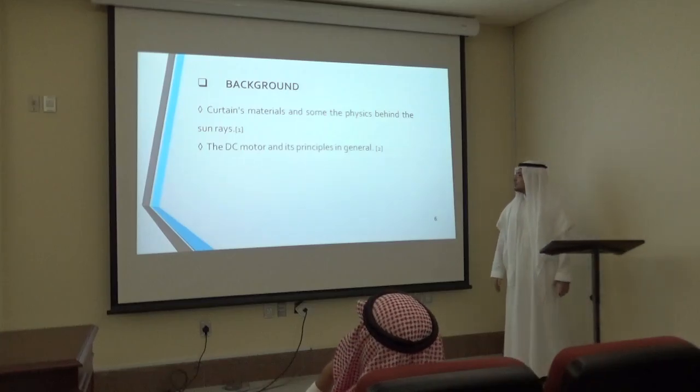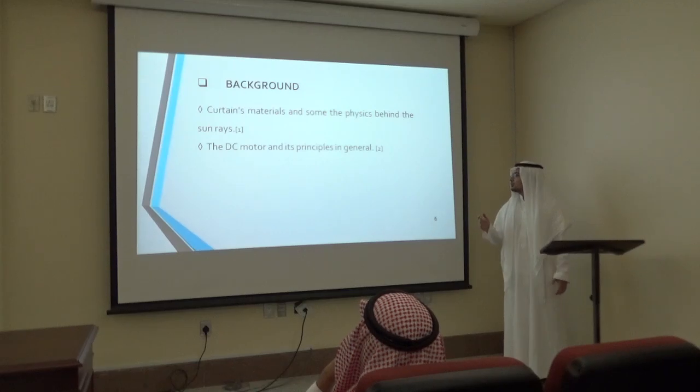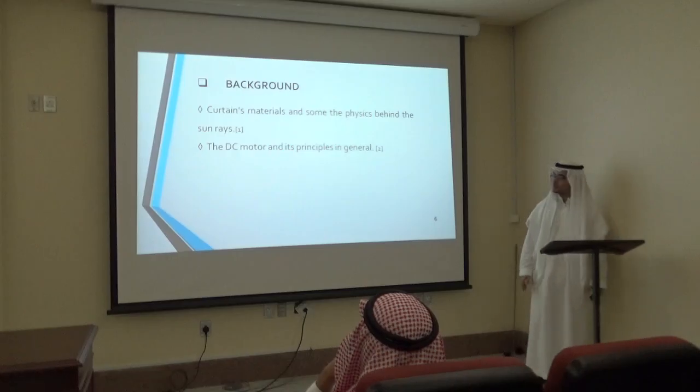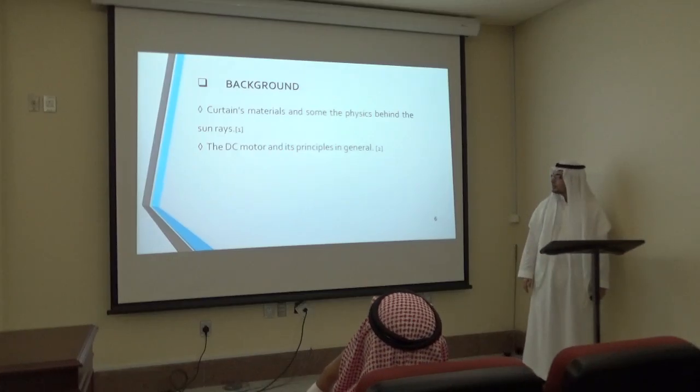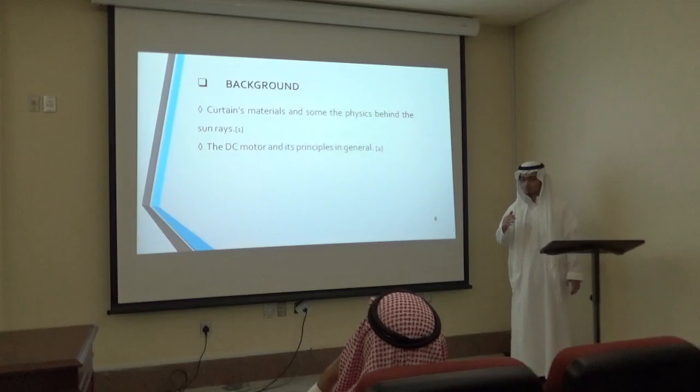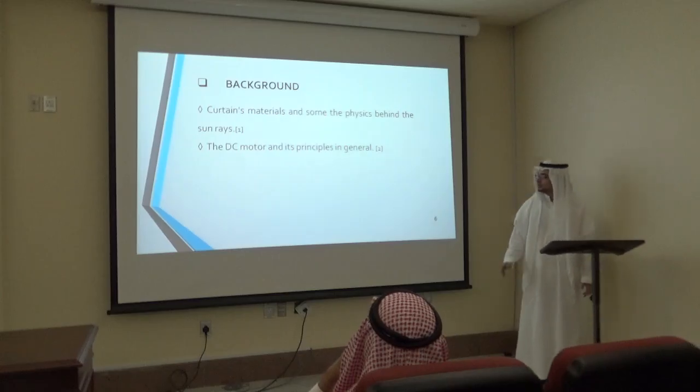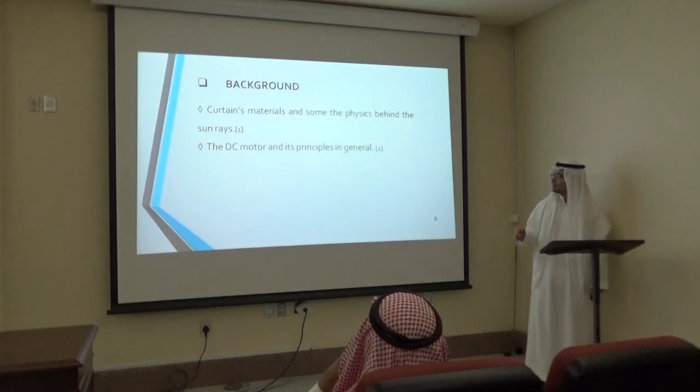The DC motor is the most common type used in many applications. The important part of the DC motor is the armature, which is the rotating part. There are other parts like the brushes and the field winding. We can control the speed of the DC motor by applying variable voltage to the armature and field winding. Also, we can change the rotation of the DC motor if we change the direction of the current. And I will leave you with my team.